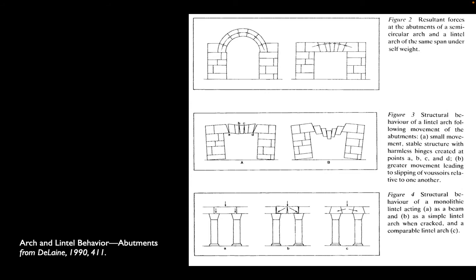Every load involves some sort of movement, some sort of acceleration, and any arch will have its buttressing walls give a little bit when load is applied on it. And as you can see, even in a flat arch, that can be fairly significant.